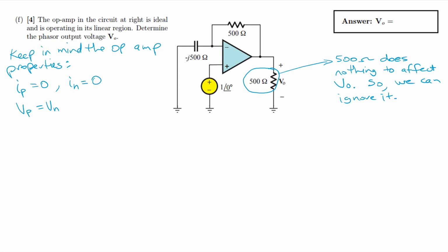Well, now let's use nodal analysis to find Vout. Nodal analysis is very useful for analyzing op-amp circuits. So when we're doing nodal analysis, we denote a node, so I'm going to call this A, and I'm going to describe the currents flowing out from every branch.